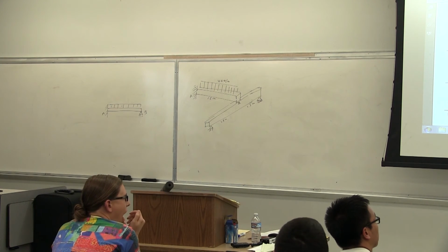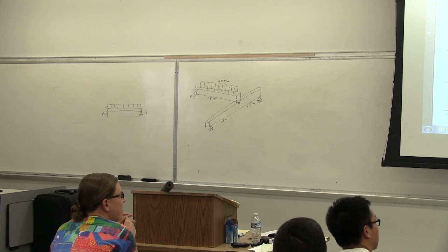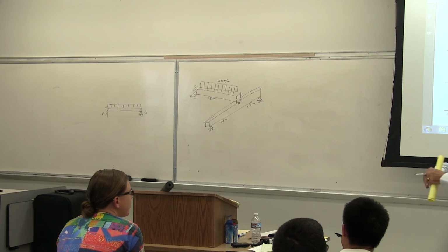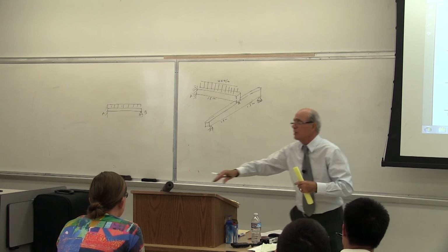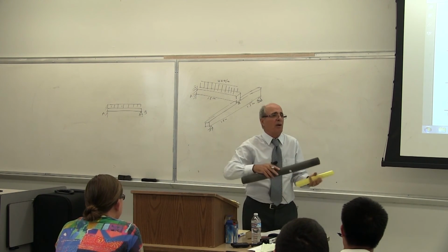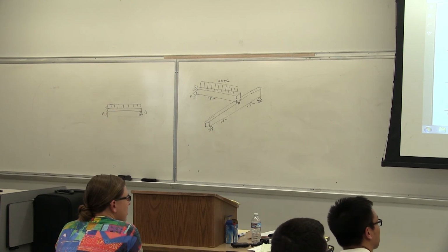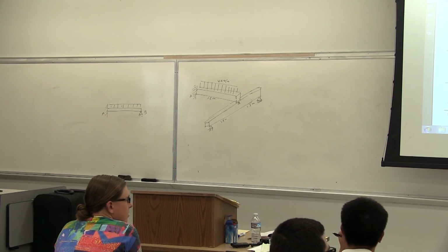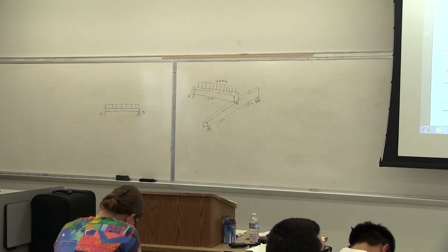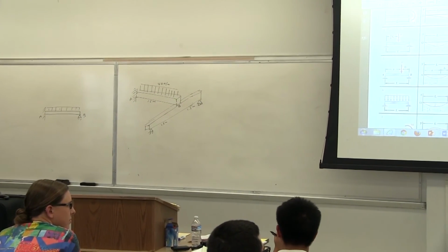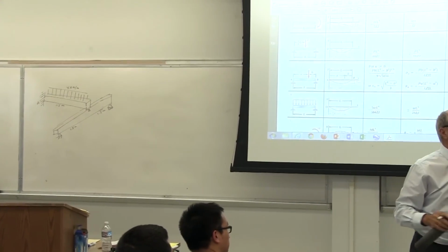It depends on the flexibility of the lower beam. If I put something like a plastic like this, which does not take much load to bend, it has no effect. If I put a concrete beam on top of that, it's going to crush this. Is that correct or not? Everybody understand that? However, if I make this of a very heavy steel beam, it's going to resist the other one. How much, we don't know.